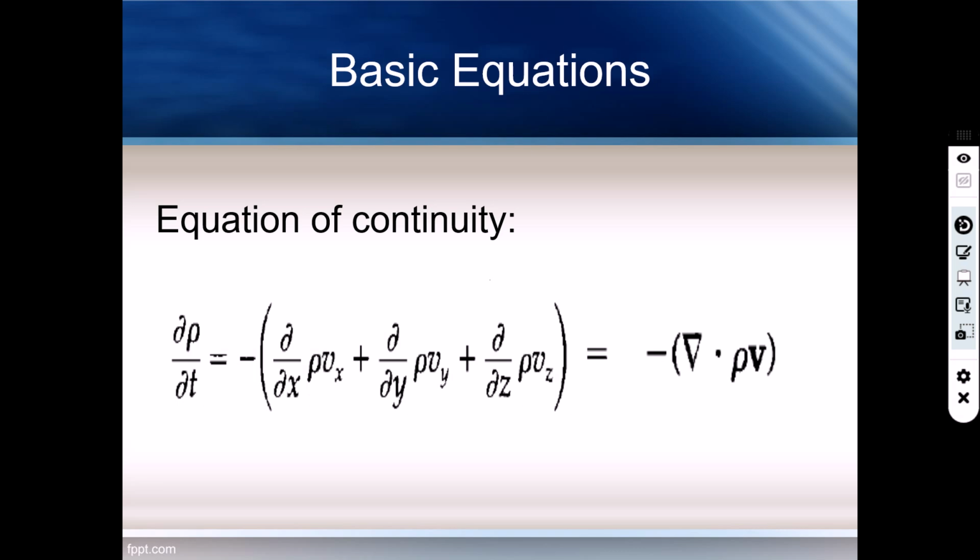But both the oil and the water are incompressible fluids, so incompressibility is not a sufficient condition for partial rho partial t equal to 0. You get the idea? Or is something contradicting your understanding?